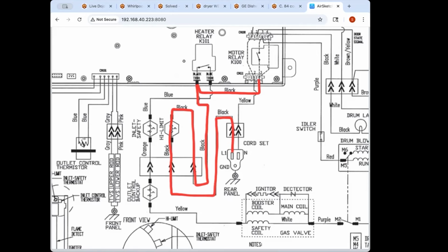It's supplying power not just to the board for its own operations, but also supplying L1 for the heater. All the current for the entire operation of the unit is going through this high limit, all your L1 current, so it's a switch under a lot of stress. If it does start getting flaky, it's very possible that it will fail under load. It may not be the problem, but it's something you definitely have to rule out.